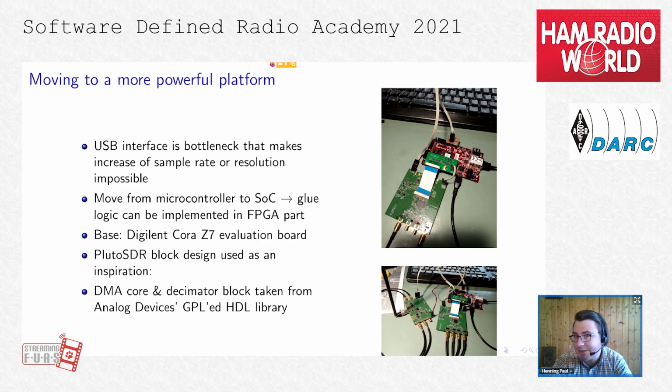So it means by using all these GPL blocks, you are able to set up a system which is quite powerful with not too much effort actually. And what you see here in this picture is now my receiver board hooked up to the same VHF receiver board you saw on the previous slide. It's a modular design. This is what I learned from my time at university. If you have a modular design, you can easily swap out transceivers for different bands, let it be VHF, UHF, or even only operate in baseband, because you don't need an up converter because the ADC is fast enough. That's what the next slides will be all about.